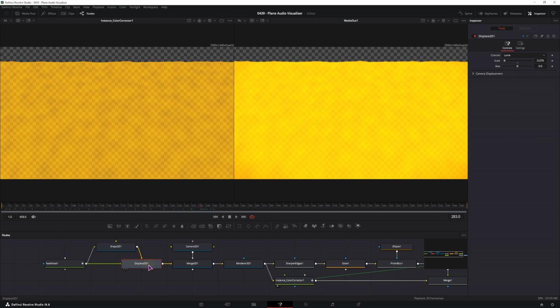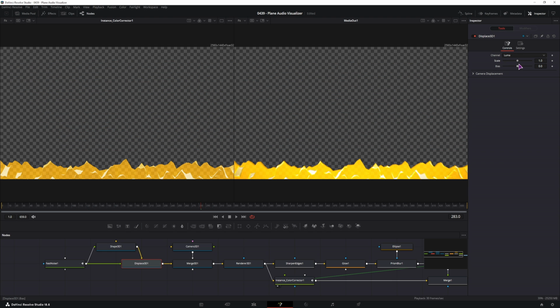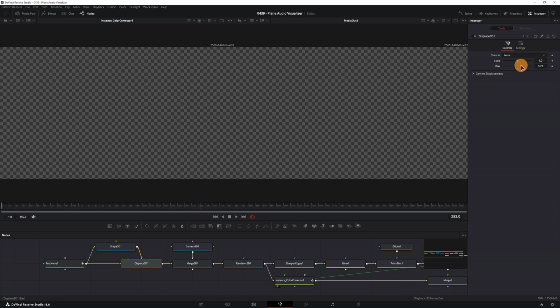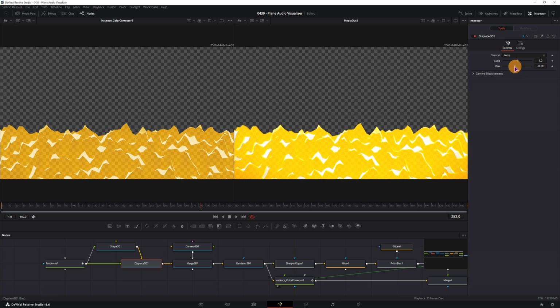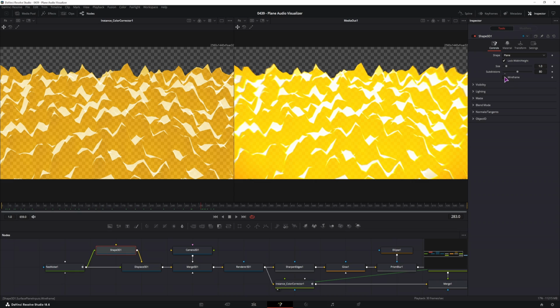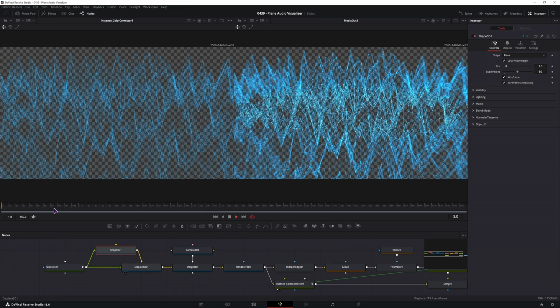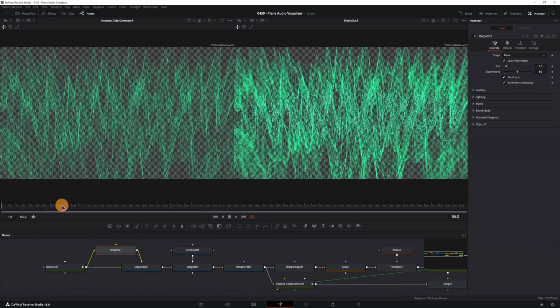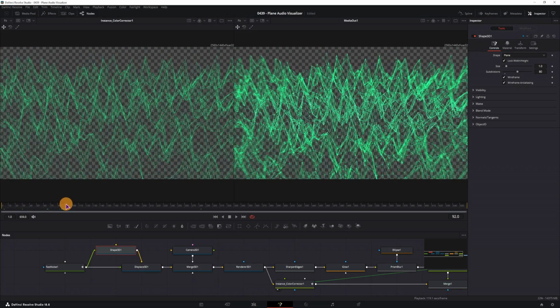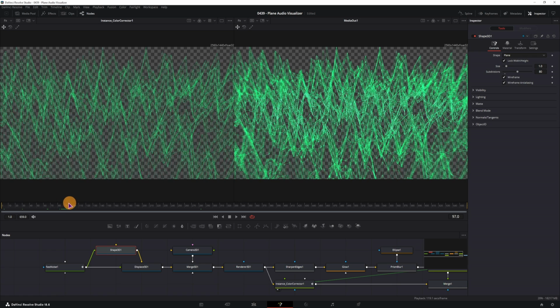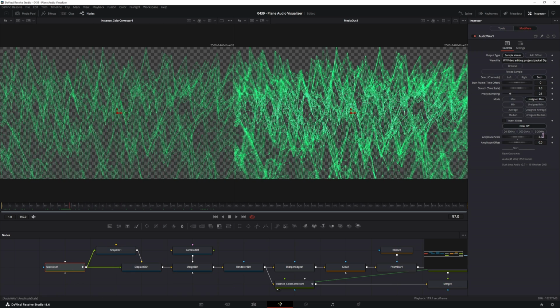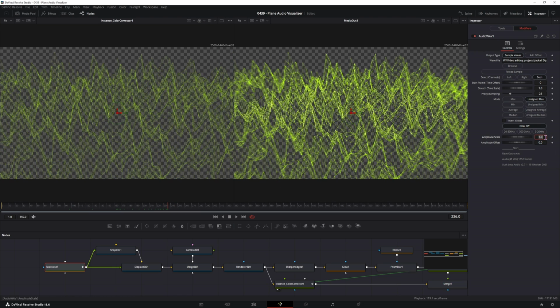And then we can also go into the displace node. What I've done previously, I've set this scale to 1 as it was, and I've adjusted the bias. And what does it look like with the wireframe enabled? Looks a bit too much. So maybe adjusting the amplitude scale, that would have to be set back to 1. And maybe at times this would even have to be maybe 0.5.